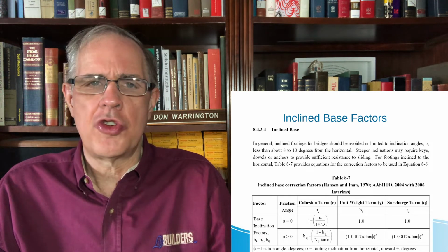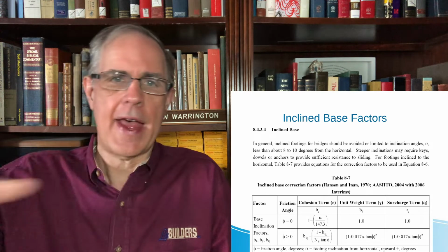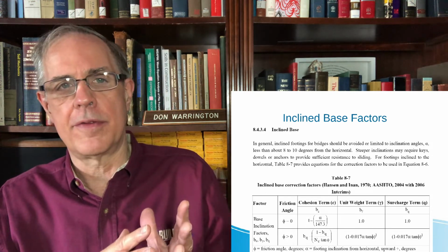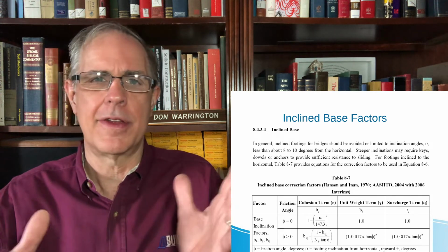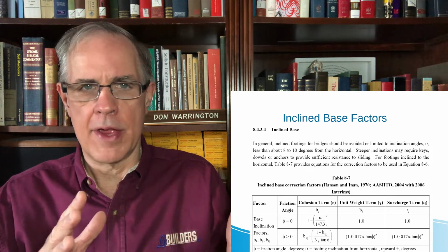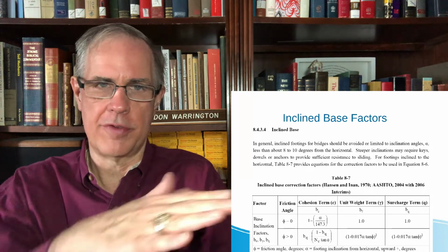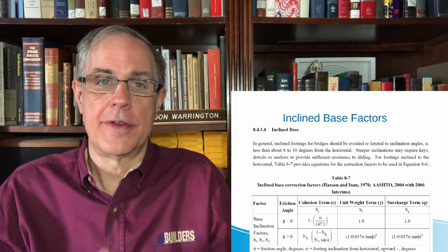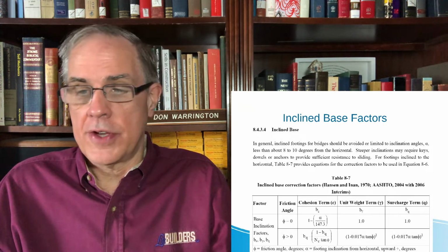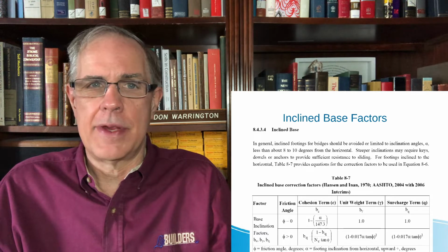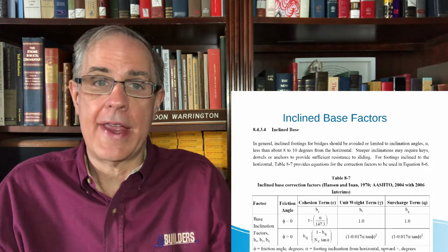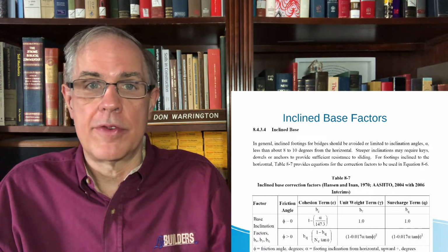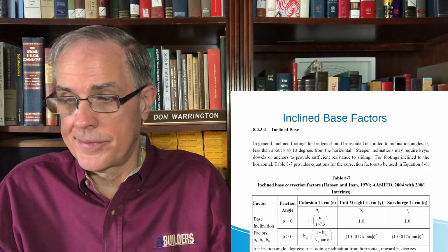If you've got a flat foundation with lateral load on it, and lateral loads and shallow foundations don't like each other very well, the only thing you have is the friction between the foundation and the soil. Well, there are other ways of achieving this. We'll talk about keys and that sort of thing. And of course, occasionally, if it's bad enough, you'll have to do some kind of piled or deep foundation to help your shallow foundation.